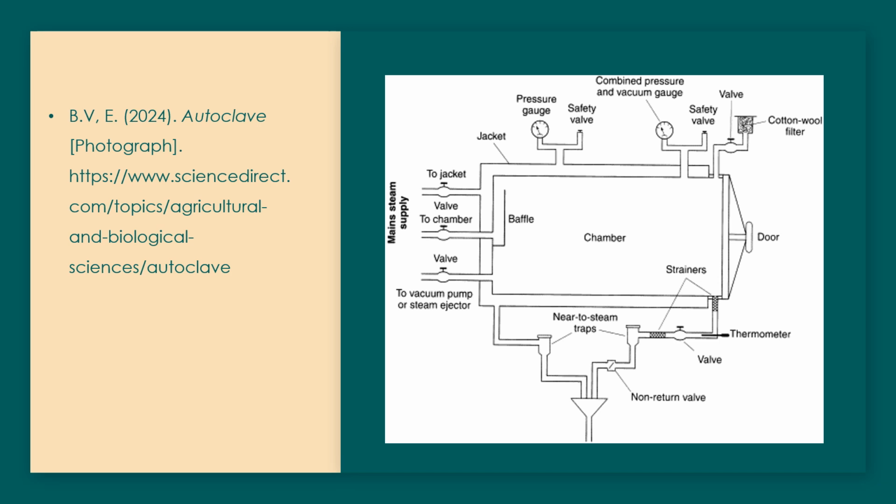Vacuum, also known as the dynamic air removal sterilizer. This is a chamber with a built-in vacuum that pulls the air out. This allows the steam to penetrate in a shorter period of time, for about 3 to 4 minutes. This operates at 250 degrees Fahrenheit.